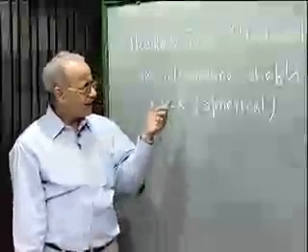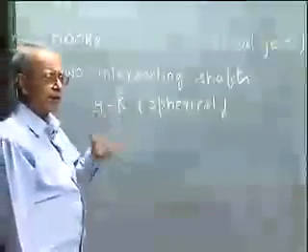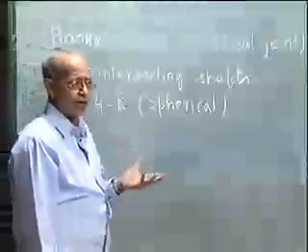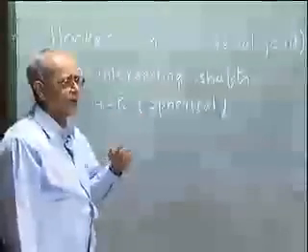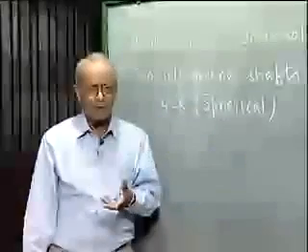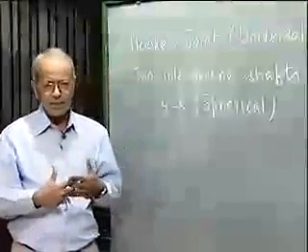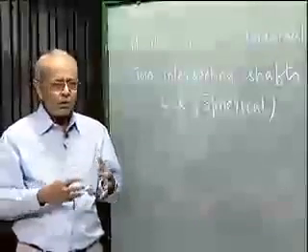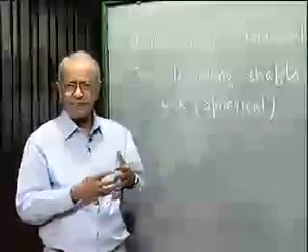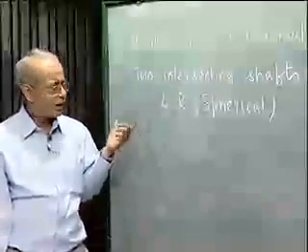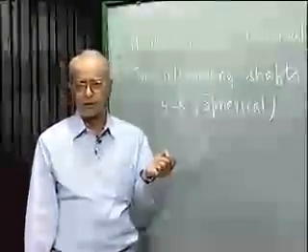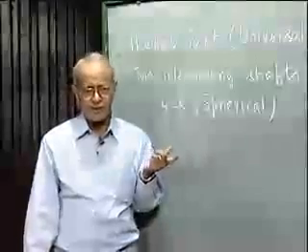Then we showed that in this kind of connection we cannot transmit a uniform constant angular velocity ratio. That means if the input shaft rotates at constant speed, the output shaft rotates at variable speed. To compensate this, we can use two such identical joints in series, and get a self-compensating universal joint which can transmit uniform angular velocity ratio between two intersecting shafts.